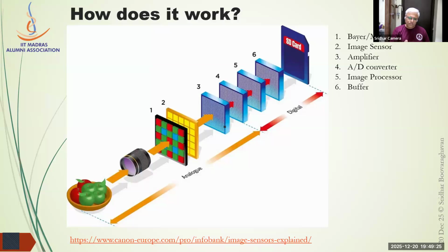Let us say there is nothing blue in that scene. The blue pixel there will record nothing, so that means that sensor will be practically turned off. So this lets in only that colored light to pass through. The sensor records the magnitude of that. If the top left is very bright, it records a high value. If it is dull, then it records a dim value.